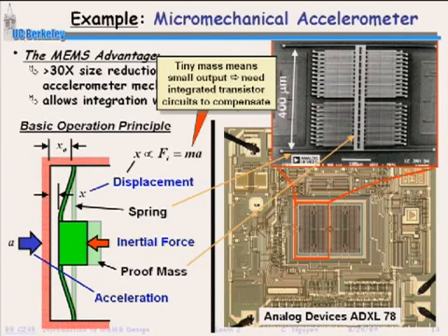So there's cons, there's pros. But I think I mentioned this before. The pro is that this accelerometer now can survive very high g-forces and can actually operate under much higher g-forces than macroscopic accelerometers. They've taken accelerometers like this, which is actually in your automobile, and shot them in missiles. Missiles explode, accelerometer's still there.